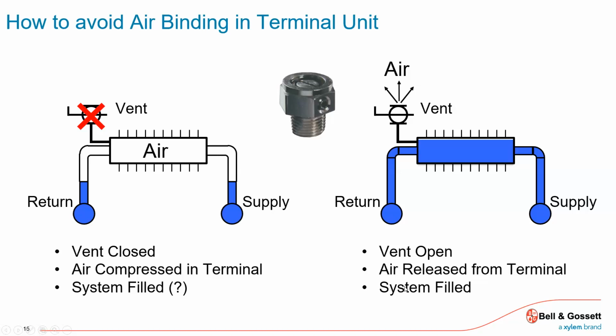What they're saying here is if I don't release it, which ideally in this case, this type of vent, they call it a coin vent or a manual vent, you'd actually manually open it when you're initially filling. In this case, maybe with a little flathead screwdriver slot, turn it, open up that coin vent right there. And as you're filling, you'd be releasing the air that right now, in this picture, got trapped. Didn't get released because someone didn't go around and vent it.